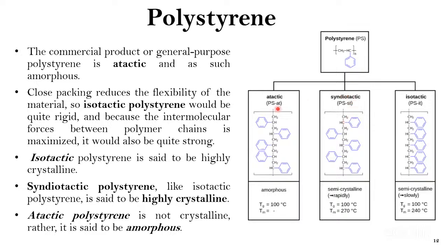Means if you compare with your atactic, this syndiotactic and isotactic polystyrene is quite strong compared to atactic polymer. Okay. That is the reason isotactic polystyrene is said to be highly crystalline in nature, syndiotactic is also highly crystalline, and atactic is not crystalline and is wholly amorphous in nature. Is there any doubt up to this?